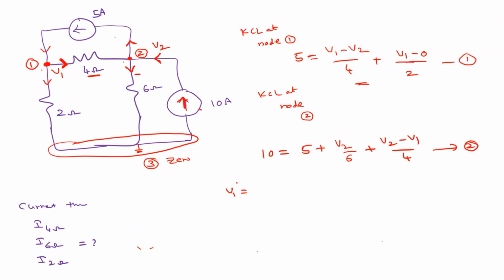So this equation is independent and this equation is independent. Okay. See here, I assume this is the one, and whether you put it on that side or this side, there is no difference. That is my point, that's why I'm emphasizing. Okay. If you are moving this one, simply it will be V1 minus V2 by 4. That's all. So I assume this is the direction. So this will be V1 minus V2 by 4.